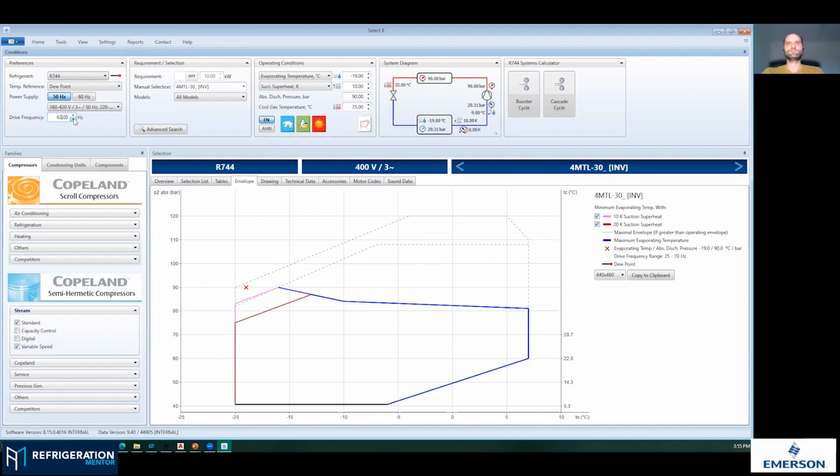So you can go to higher discharge pressures and also to a bigger compression ratio. It's basically because of the size of the motor, which has to give you bigger power at a higher speed. So that's why it's limiting the envelope, with the reflection of the nominal horsepower size, and also the influence on the temperatures is there as well.